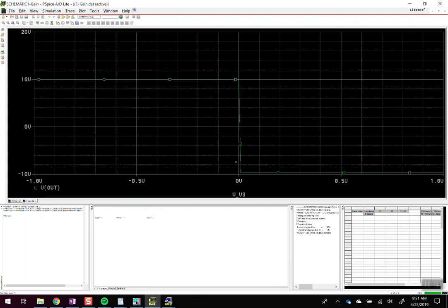Now, the one thing that's not as great about this particular design is our linear region isn't centered around 0 volts, which is what we'd like, but that's where you have something that's called, if you ever remember, they're talking about these, like a 741 has this offset null and other things of that nature, where we can shift where that load line is just by applying additional DC voltages to the circuit in appropriate places.